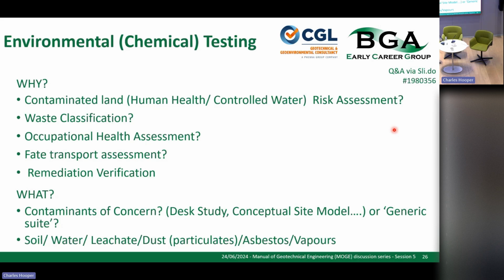But you can also look at the site history. Say there was a gasworks half a mile down the road and you've got an infilled hole. Are we likely to get gasworks waste in that hole? Depending on when it was infilled, I would suggest possibly. If the gasworks was operational in the 1950s and a hole was infilled in the 1950s, somebody might well have shoved their stuff in that hole. So you can be prepared and look for what you need.